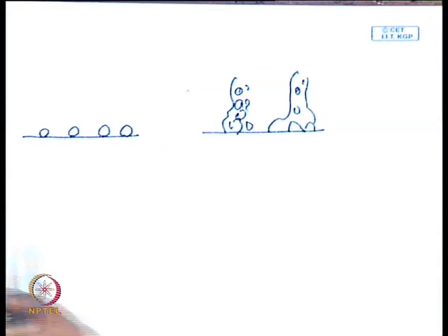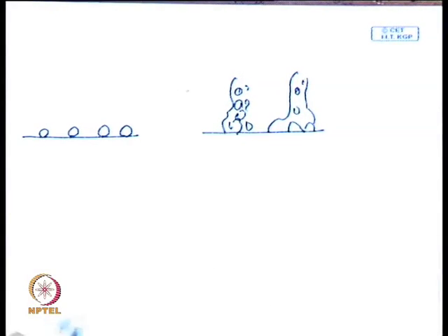Another thing is important, that the generation of isolated bubbles is crucial for the process of boiling. Why is it crucial? Because these slugs and columns are ultimately coming from the isolated bubble, and for the isolated bubble there are many physical processes involved. If we analyze them properly, then probably part of the boiling process is clear to us. So, next I will devote some time to bubble nucleation, its growth and collapse.